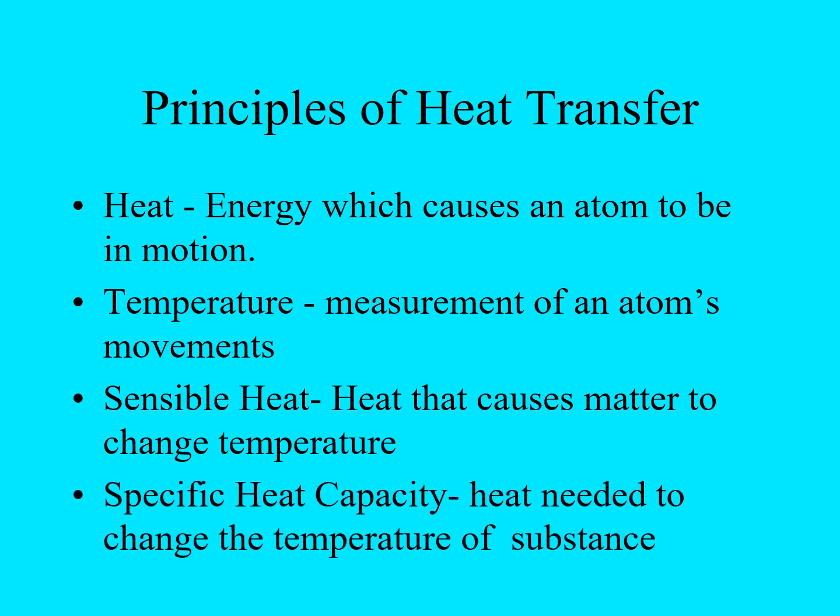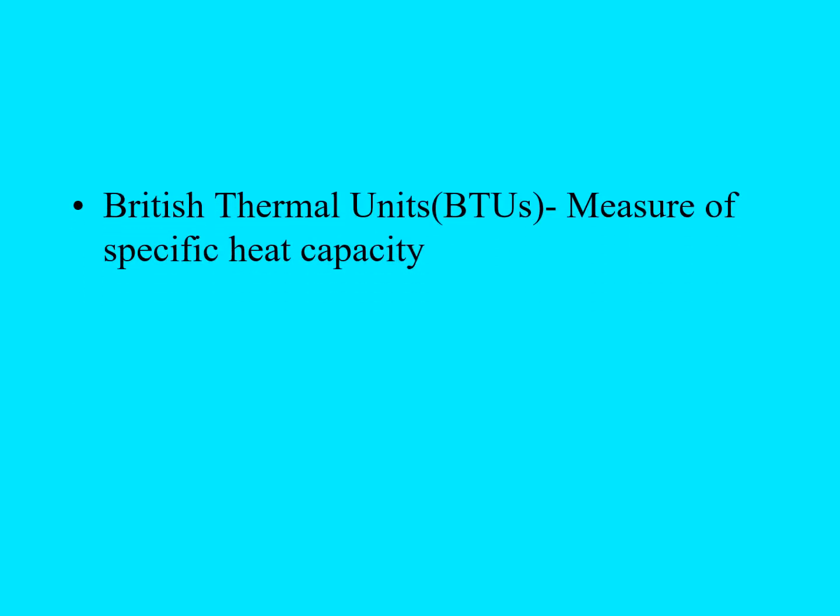Then we have what's referred to as specific heat capacity, and that's the heat needed to change the temperature of a substance. And BTUs is what we use as the standard unit for the measurement of heat capacity. So 1 BTU would raise the temperature of 1 pound of water 1 degree.